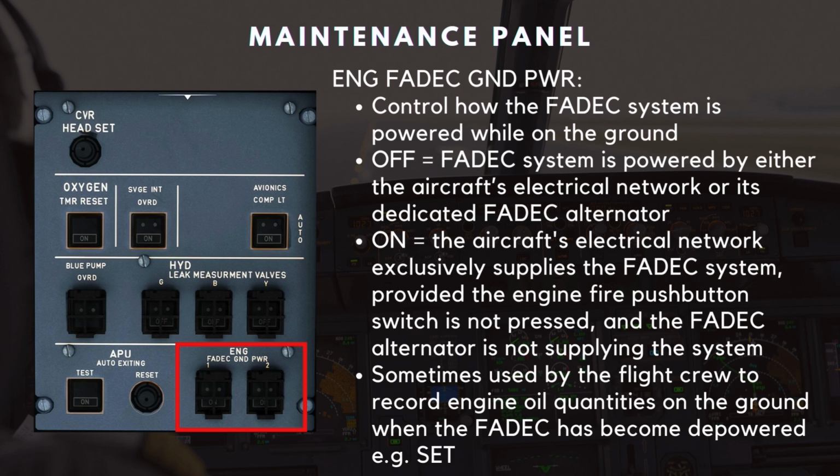This is sometimes used by the flight crew to record engine oil quantities on the ground when the FADEC has become depowered, such as after a single engine taxi or for extended periods on the ground when the engines have been switched off.